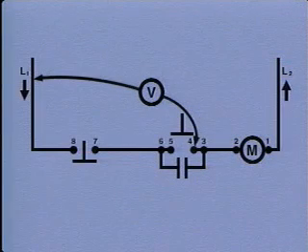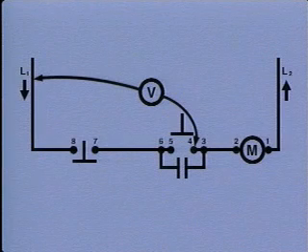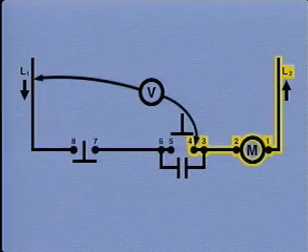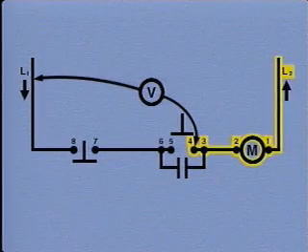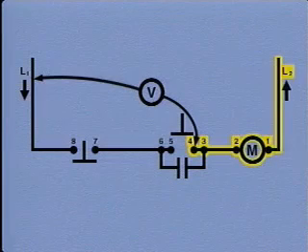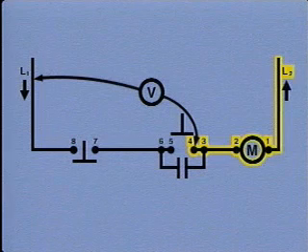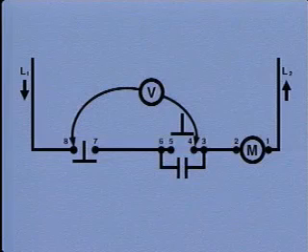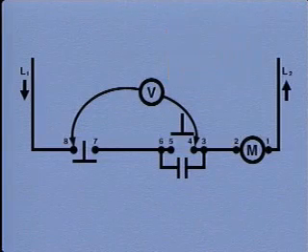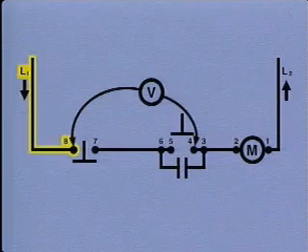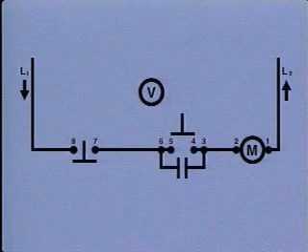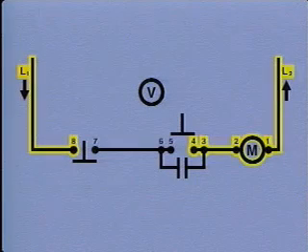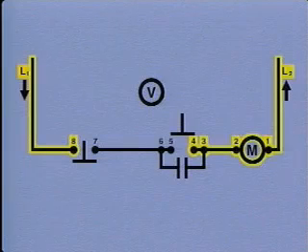The next test is made from L1 to connection point 4, and the voltage tester again indicates full line voltage. This means that there is a complete voltage path from L2 to connection point 4, so the wiring and components from point 4 to L2 can also be eliminated as a cause of the problem. The next test is made from connection point 4 to connection point 8. Again, the reading is good, so the electrician knows that the wires from L1 to connection point 8 are okay. At this point, the wiring and components from connection point 4 to line lead L2 and from connection point 8 to line lead L1 can be eliminated as the cause of the problem.